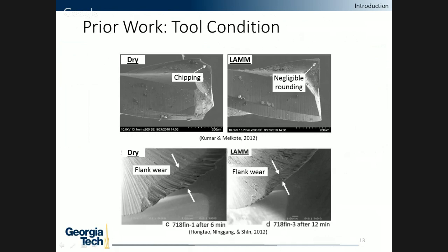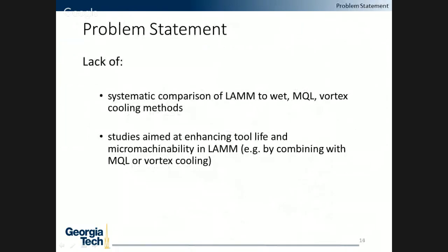In another study, in the cutting of Inconel, it was shown that in the dry case, there's significant flank wear, but with laser assist included, there is significantly less flank wear.